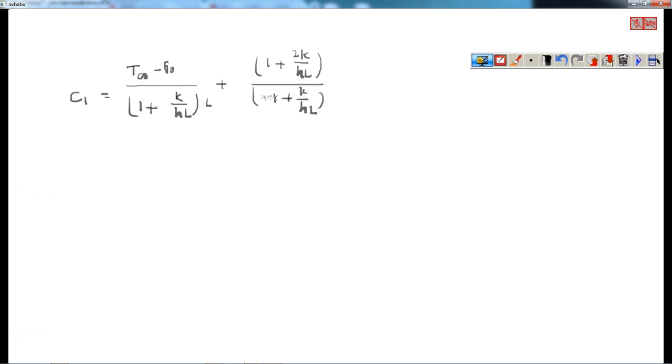So now, substituting C1 and C2 with T2, the general equation. What is the general equation? The temperature general equation is T equals minus q dot by k x square plus C1 x plus C2. In that, if I substitute C1 and C2 in the equation, then T is equals to general, T is equals to, I'll write it here, T is equals to minus of